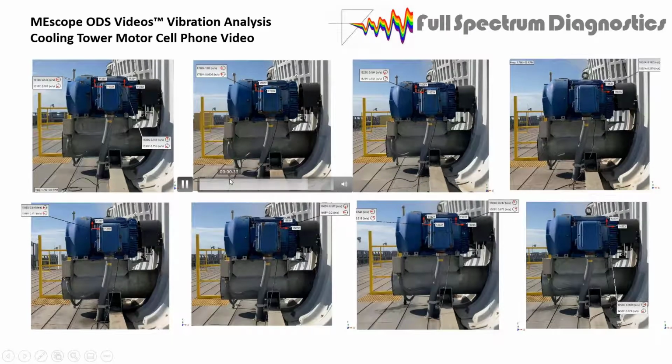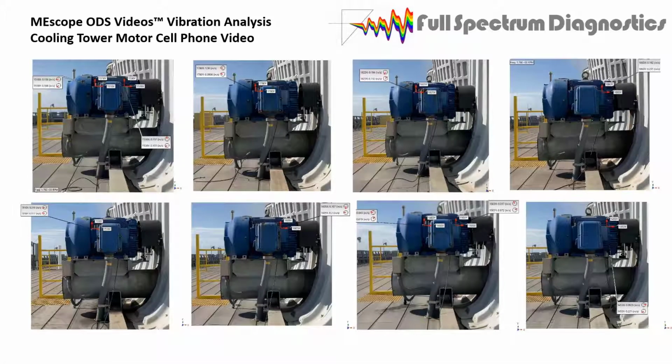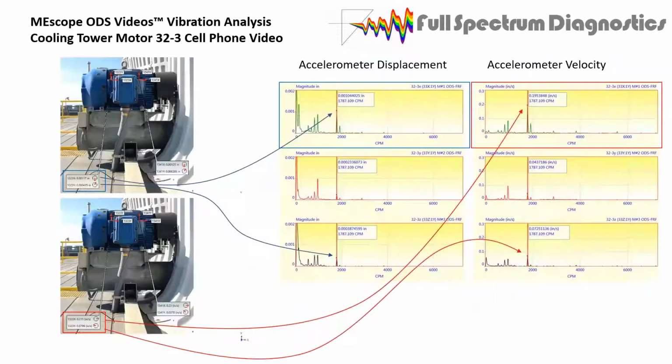If you do want to get a little more into this and get a little more precise, put a transducer on there, take your measurement, and then take a video and leave the transducer there. And now you can directly compare the location with the amplitude for the video and scale accordingly. And a couple pictures, just like I started before with the other camera and the close-up view. I have a displacement plot showing the X and Z directions, and I have a velocity plot. I differentiated the data, it's push of a button on the fly type stuff. And now I have X and Z type vibration, okay?